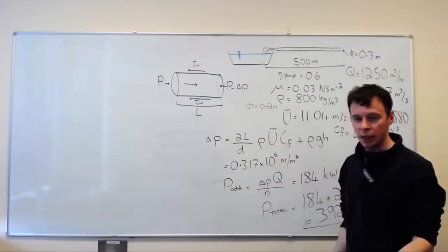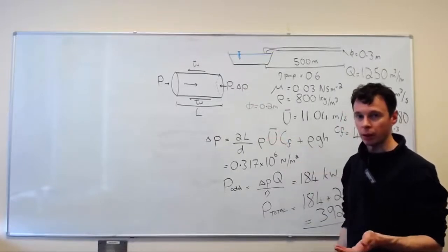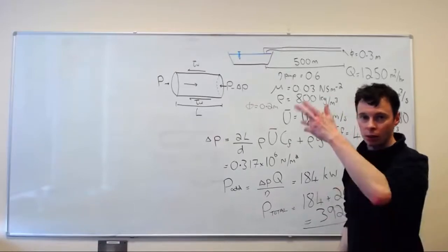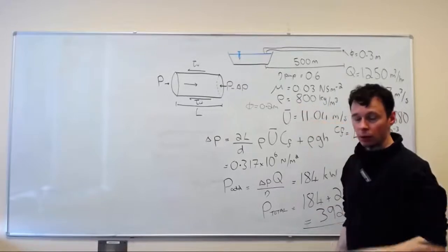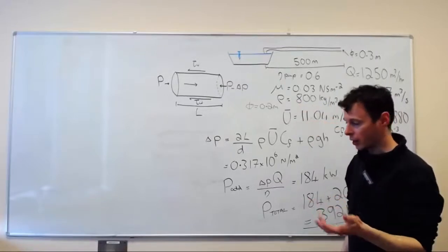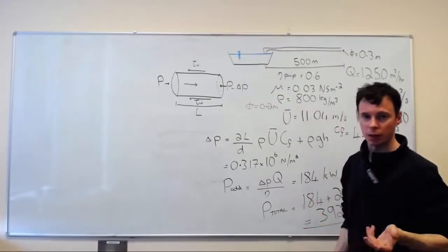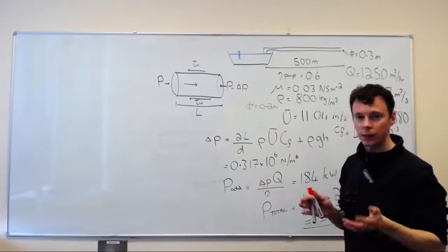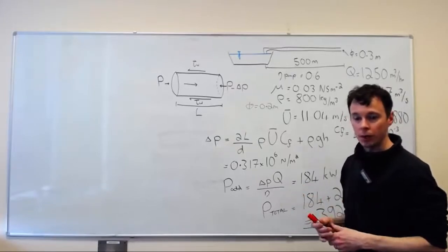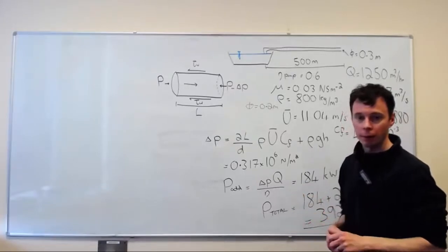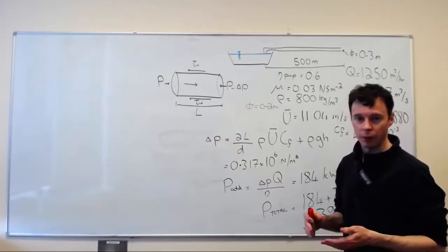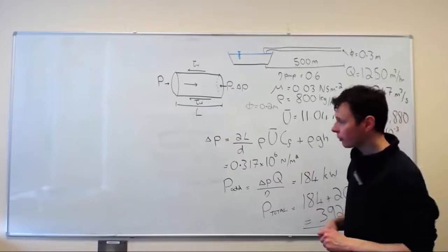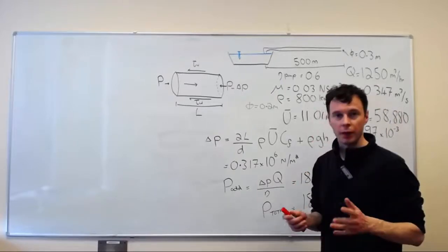But ultimately, when you get to, say, the base of a tower block or a multi-storey building, you have to lift the water to the highest floor that requires water, usually the top floor, and that water has to come out and be supplied at a certain pressure. So in the UK, that's approximately 10 metres head. So you've got a 30 metre tower block. You need to make sure that at the bottom, you're delivering water at a pressure of 40 metres.